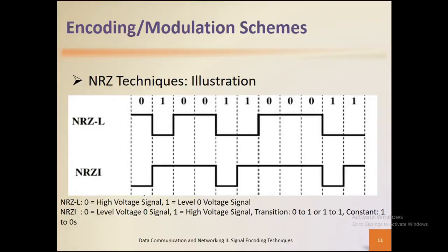Okay, but at the initial bit sequence state, notice that 0 is level and 1 is high. So assuming that the bit started with 1, then you'd have a high voltage pulse over here. And if the next one were to be a 0, then what happens? Because you have a 1, 0. Now there's no transition within 1, 0. So you just basically move on to what? A low voltage pulse to indicate the first two stages of the signal representation at the bit levels.